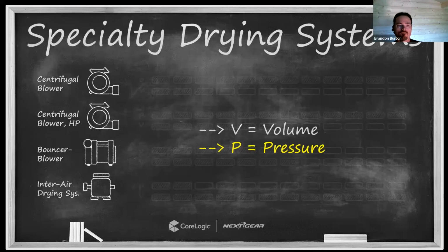The second thing about that amount of air, before I get down to pressure, is also how quickly it moves across the wet surface. The nice thing about interstitial spaces, though, is that they're relatively small, right? And as long as I have a good rate of exchange through the space, then air is going to have some velocity across the surfaces. It doesn't take a lot of volume to create a good rate of movement through an interstitial cavity space, at least most of them, those that are relatively small, especially like a hardwood floor, for example.